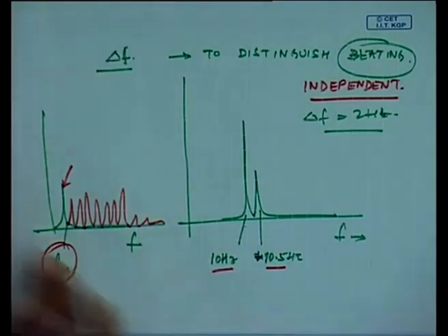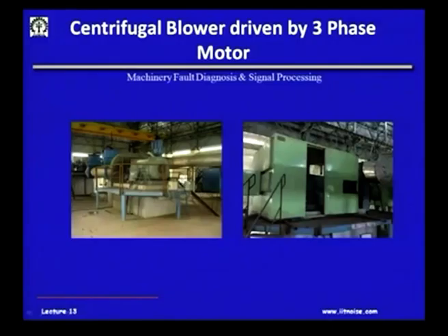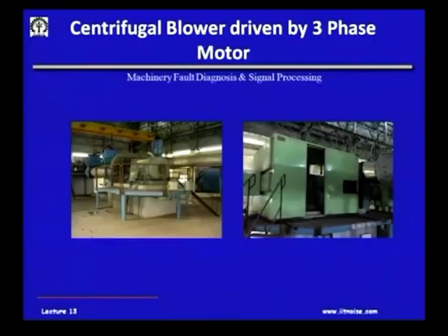Okay. Now, in a plant like this, I should just mention to you that in fact, we at IIT Kharagpur had designed this enclosure for them just to kill this noise which was generated because of the beating. Because again, if I have one machine generating 100 decibel of noise, another machine of course another 100 decibel of noise, the sum effect will be 106 decibels, but because of beating at some frequencies there will be a large amplitude and that amplitude will be very, very loud. So, to reduce that we can put an enclosure wherein you can put in a lot of lining material.